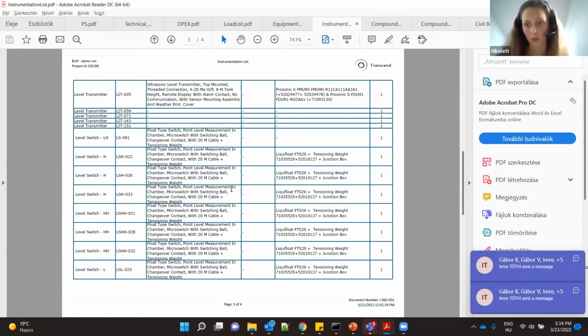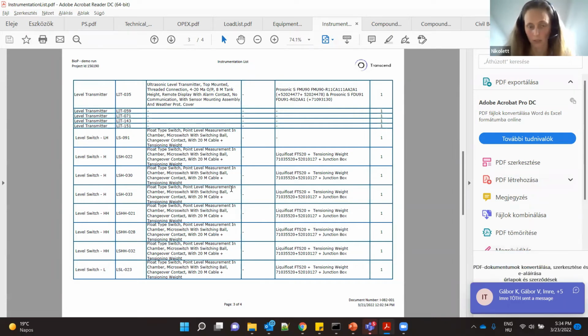Of course, in later phases of the project, when you have detailed information regarding the influent concentrations and fractionations, within the tool, we provide some fractionation, because we have to be able to run the simulations. But that fractionation is just considering some typical fractions, which are commonly there for most facilities. If it turns out that you have a different fractionation, that can influence the design, but that comes in later phases.